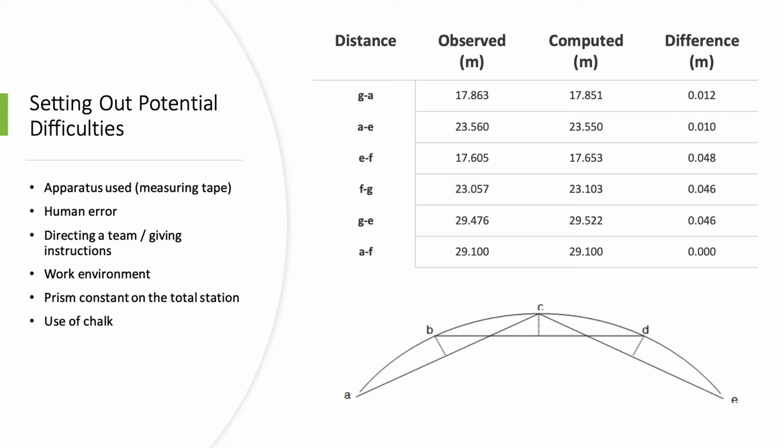With the given easting and northing coordinates of the points, the quality assurance was carried out by computing distances of 4 sides and diagonals of the stage using coordinates and comparing them to the measured values. Overall, the observed and computed values had small differences between the 2 sets of data. The differences between computed and observed values vary between 1 and 5 centimeters, which is not significant in relation to the scale of the measurements, which is 17 to 29 meters.